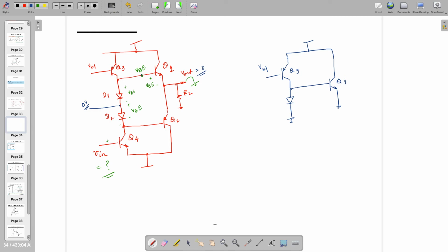So now this is actually a diode circuit. Diode is nothing but, if you remember, you can implement a diode using such a configuration where base and collector are tied together. When you are doing such things, the current flowing through this one and this one depends on what ratio of diode and Q1 geometry you are keeping, right?